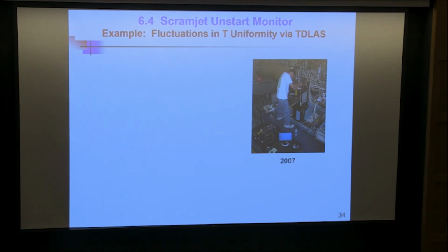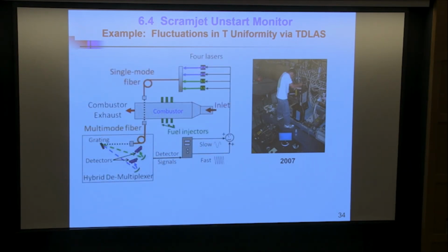One of the problems with scramjets is if you release too much heat, it causes what's called unstart. The shock wave will come back up, or instabilities will come back up, and it'll cause choking of the inlet. So one of the discoveries Greg found was interesting. He used four lasers, two pairs. Each pair gave him temperature, so we got two temperatures. One pair is sensitive to low temperatures, one pair was sensitive to high temperatures. What we wanted to look for is how well we could measure temperature, and when those temperatures changed, because there was some cooling along the wall, a precursor to unstart.